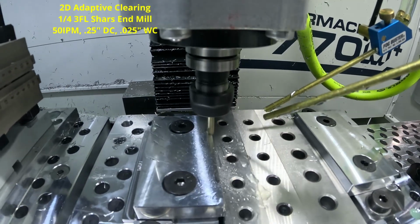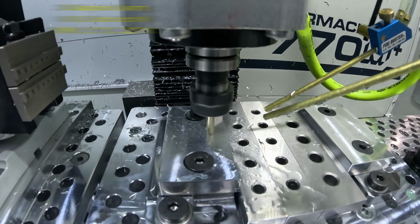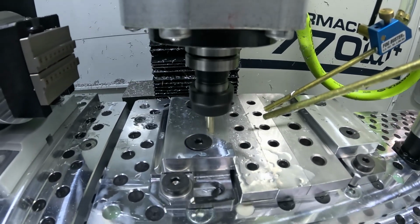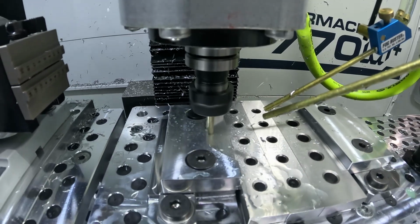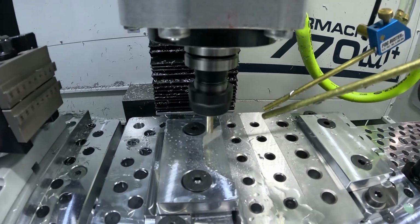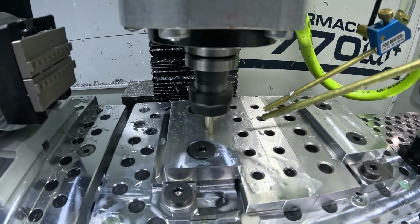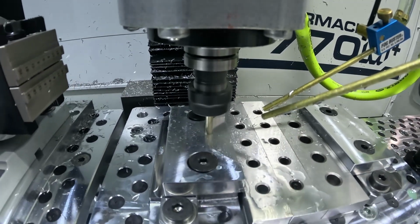Again, you need to make sure yours is 4 inches. That way you have some clearance for op 2 so that the screws you see at the top of the movable vise jaw on the left, you have clearance to tighten those. So now what we'll do is begin transitioning into our 2D pocket.